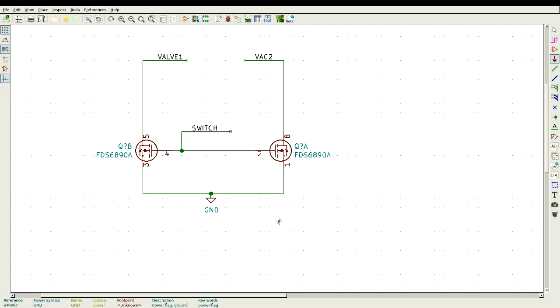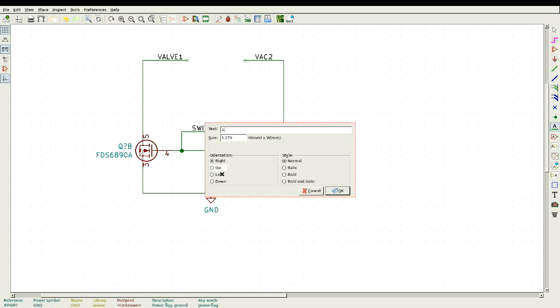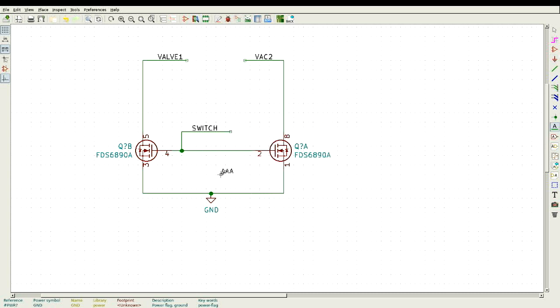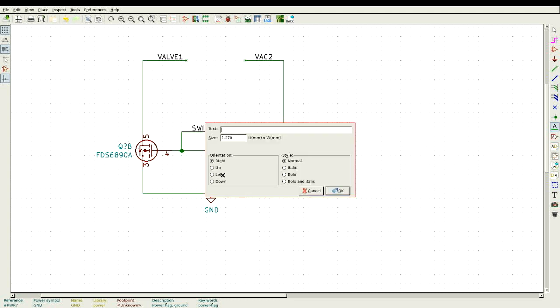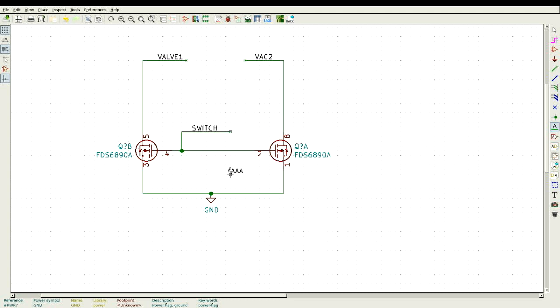Question? Did you have to place the cursor on the wire before you added the label? No, I don't think so. Let's see, if we just go, no. So it's attached to the cursor, and it'll wave round, and then when I left click, it'll drop it down. How is that being associated with the wire? The label. Yeah. You see there's the crosshair there. So when you drop that on a wire, that's now associated.